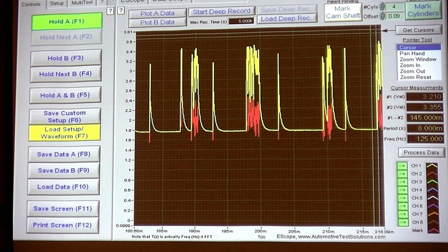These guys didn't wake up. One woke up, didn't it? The tranny controller. So the tranny controller isn't the one I'm worried about. I'm wondering what's in common with the other modules. Start looking at a wiring diagram. Look at the powers and see if they're connected. See who all powers the same modules. You understand? Because this is a power problem.